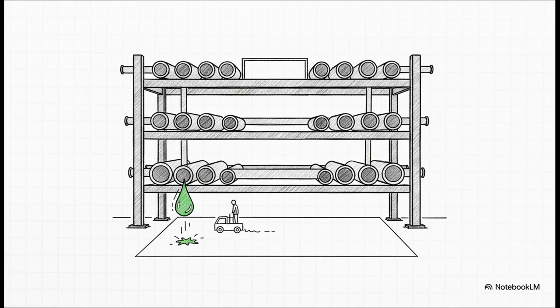So why so many rules for a simple rack? Well, it's all about planning for the future and planning for failure. Leaving 20% of the space empty might seem wasteful now, but it's a lifesaver when you need to expand later. And putting the pipes with corrosive stuff on the bottom level? That's just common sense. If it leaks, it just drips on the ground, not all over everything else below it. It's all about thinking ahead.